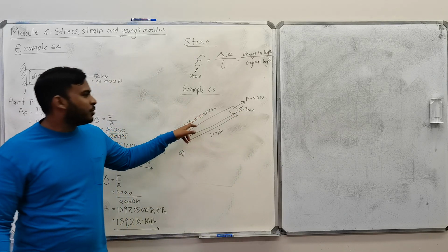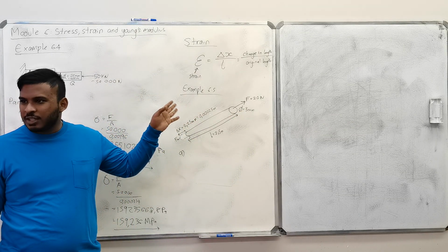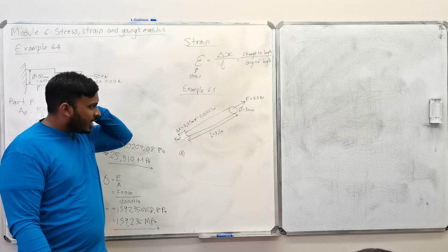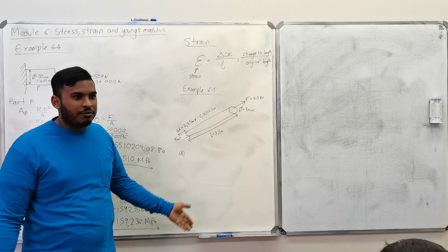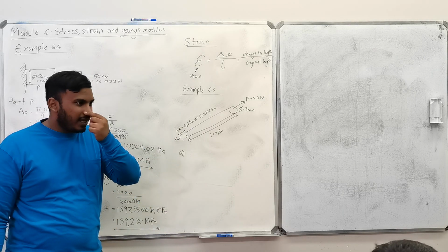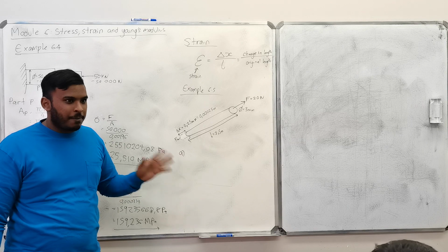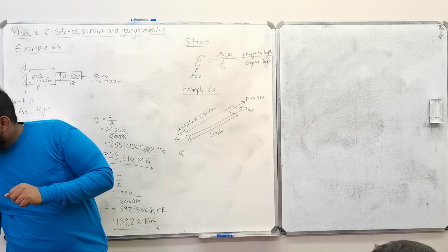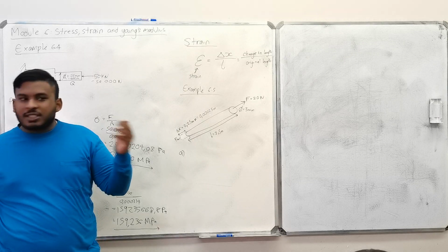I'm saying the 0.25 millimeters in meters is 0.00025. So the new length of the wire is actually 2.50025. Right? I understand the concept of it. Okay, so what's the question? Calculate the stress in the wire.